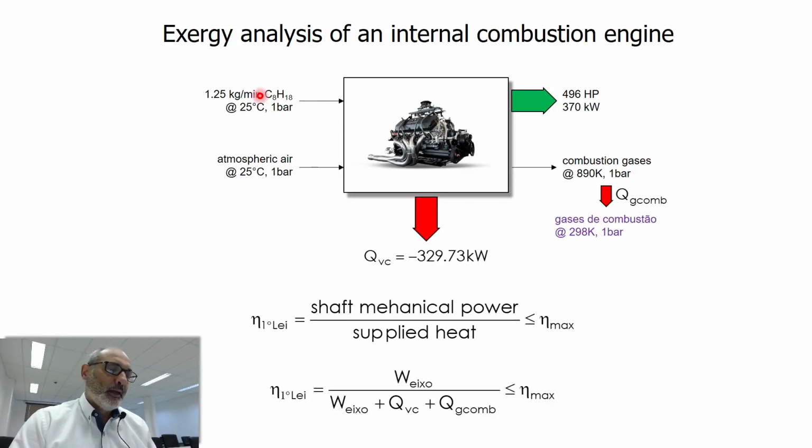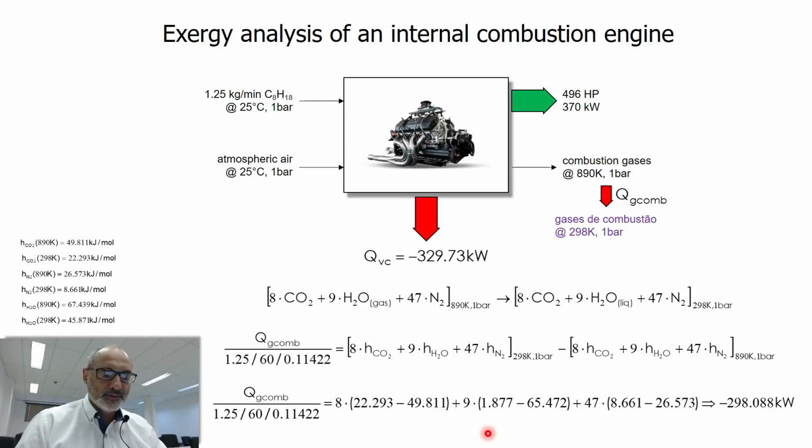I can calculate from the heat content of the fuel, but I also can make this energy balance here, because the total supplied heat is equal to what I have here as shaft power, plus what's being removed here, plus what's associated with these combustion gases here. So let's try to assess. We know this, we already calculated this. Now let's try to assess this one.